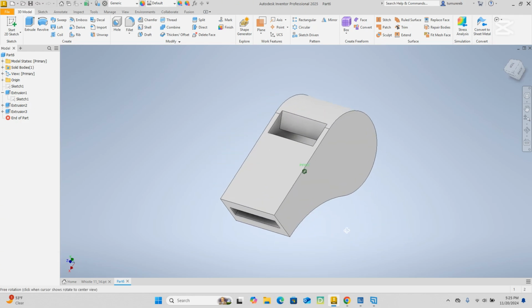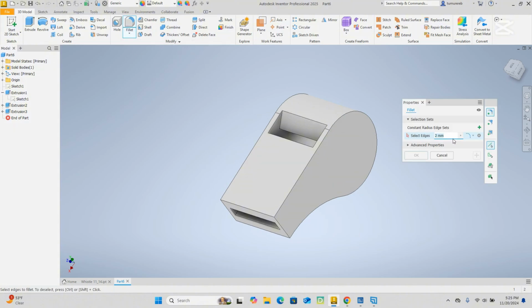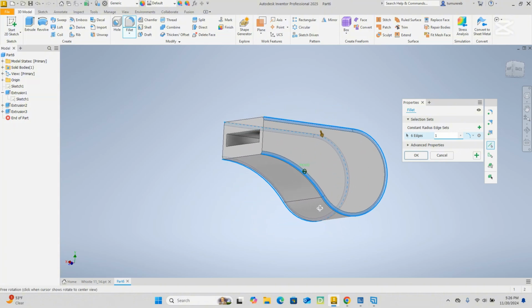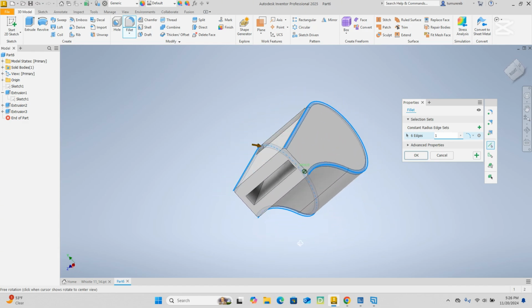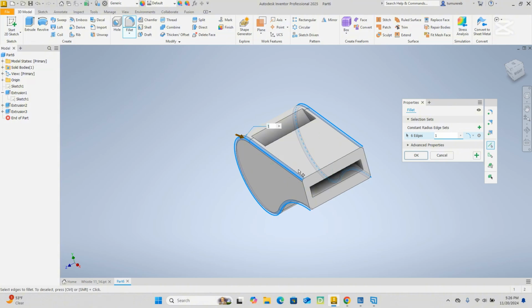Almost done. Now let's go ahead and fillet. I know you're hungry. Filet mignon. Chick-fil-A, whatever meal you like. What's the radius? Let's do 1. Just 1. Type in 1. So the radius is 1. Select that profile. Select that edge. Okay. That's for aesthetics, utility, or safety reason, but it can still work. Okay. Alright. And then click OK.